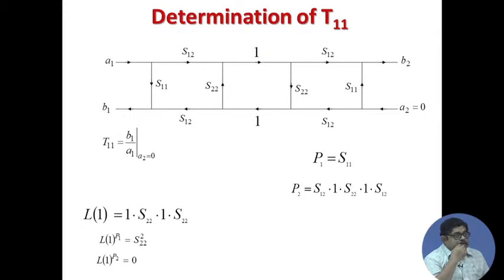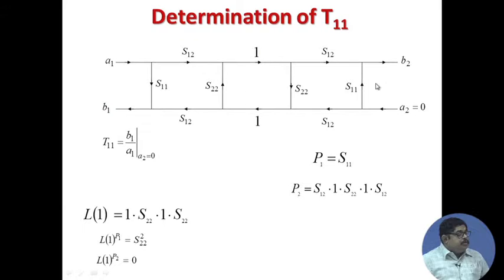Now, come to the T matrix. So, this was the signal flow graph here, we will apply Mason's formula. What we are trying to find, when we are trying to find the T matrix, is basically something like an S matrix, scattering parameter. It is together the scattering parameter of the error boxes on the two sides and then the through connection.